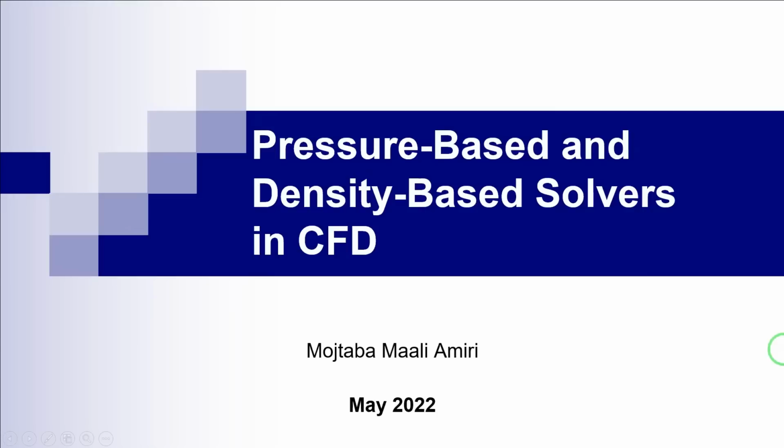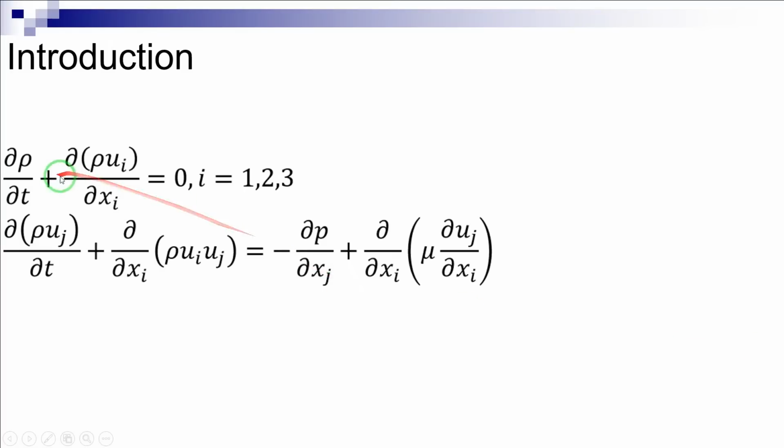Hi everyone, today I'm going to talk about the pressure-based and density-based solvers in CFD. Both the pressure-based and density-based solvers are used to solve the mass and momentum conservation equations which describe the fluid flows. Every fluid flow must satisfy the equations of continuity and momentum as shown here in the differential form.